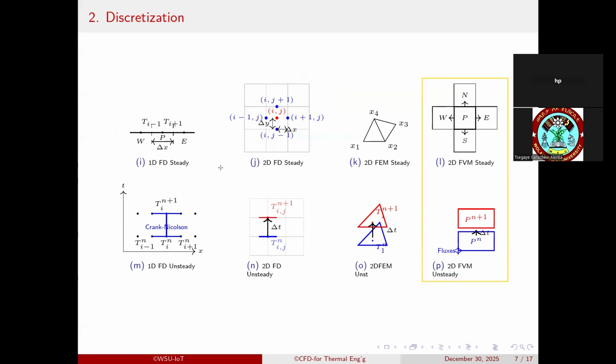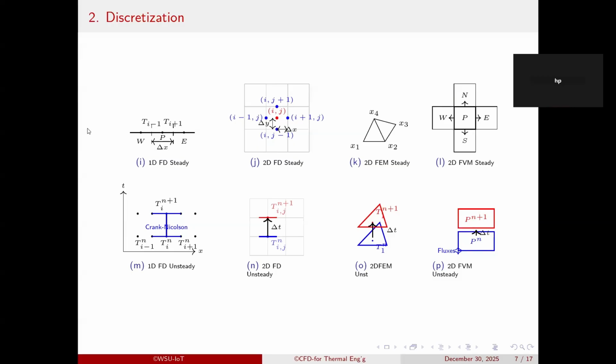This method offers consistency of conservation, ensuring exact global and local conservation at the discrete level, and less memory usage. In other words, the finite control volume method is that with which all three conservation equations can be expressed as a single generalized transport equation.